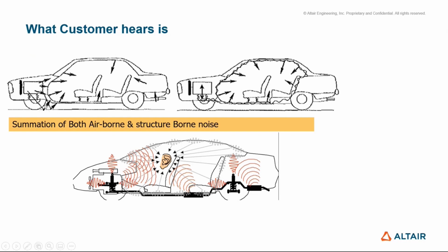For example, because of tire rotation you get tire horn noise or road noise, or engine combustion noise which propagates through the air inside the engine bay region and transfers into the cabin. Just like if you talk in one room you will hear it in the other room, even though there is no vibration, it gets transferred. This is because of the mass law transmission, and it is a major path for airborne transfer. To solve such problems, you need to use SEA, which can help you solve up to higher frequencies, because generally airborne propagation happens at higher frequencies.